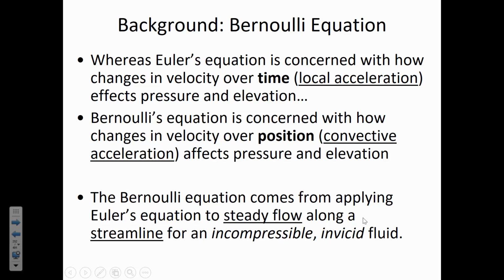And finally, this last assumption is that the fluid is inviscid. Anybody want to venture a guess of what an inviscid fluid is? That's right. An inviscid fluid is one that has no viscosity. Do you know of any fluids that have no viscosity? I don't. There is no fluid that has no viscosity. There are some fluids that come pretty close, like gases, which have a really low viscosity. The corn syrup that we just saw has a pretty high viscosity. Water has a lower viscosity than corn syrup, but gases have an even lower viscosity, many orders of magnitude lower.